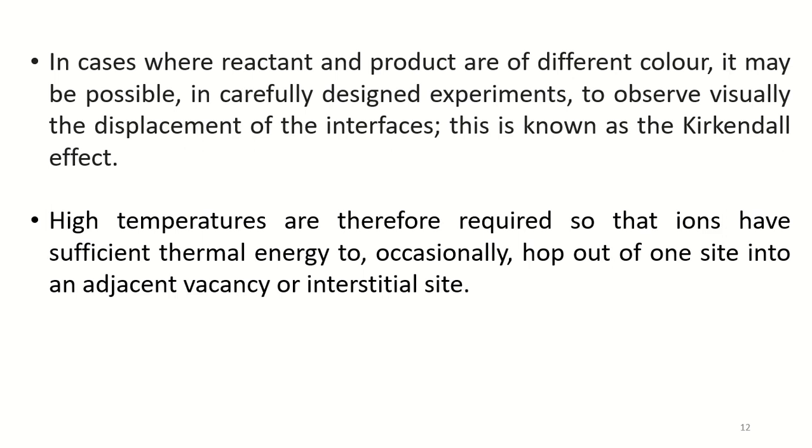The spinel formation reaction is particularly slow because ions, for example magnesium Mg2+ and aluminium Al3+ ions, diffuse very slowly. Typically, heating for 1 week at about 1500 degrees Celsius would be required to form a fairly pure spinel product.